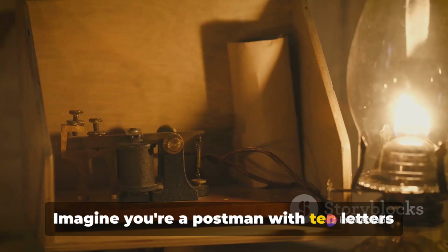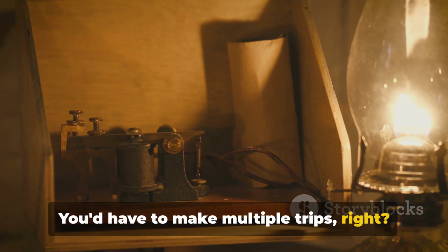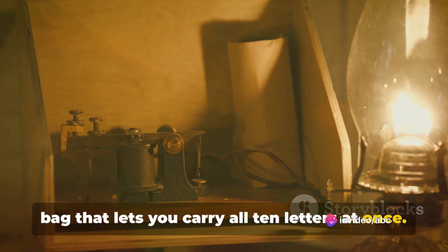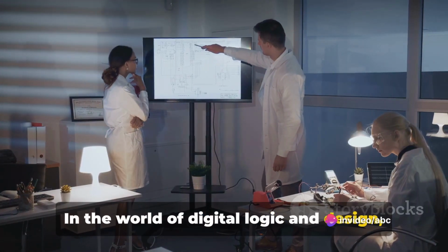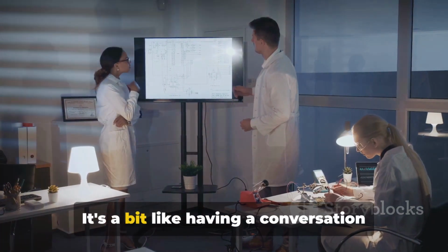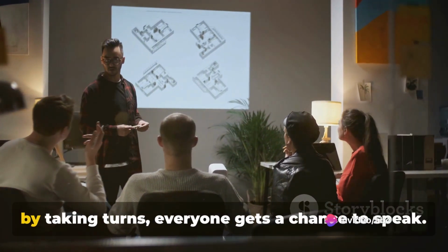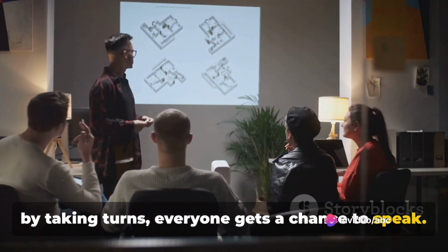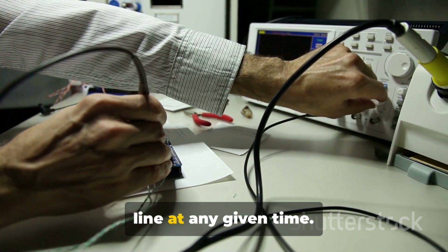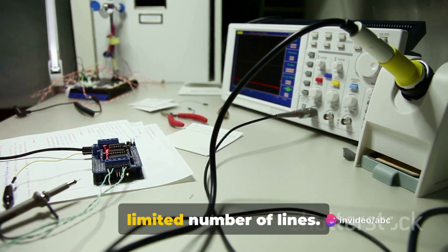Imagine you're a postman with 10 letters to deliver, but you can only carry one at a time. You'd have to make multiple trips, right? Well, multiplexing is like having a magic bag that lets you carry all 10 letters at once. In the world of digital logic and design, multiplexing allows us to send multiple output signals over a single line. It's a bit like having a conversation over a walkie-talkie. Only one person can talk at a time, but by taking turns, everyone gets a chance to speak. Multiplexing relies on a control signal to decide which output gets to use the line at any given time. This way, even if we have a multitude of outputs, we can still get by with a limited number of lines.